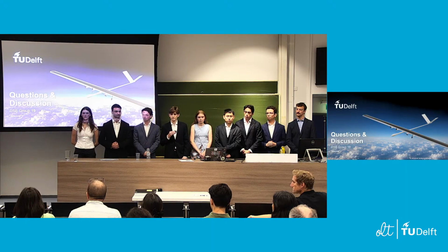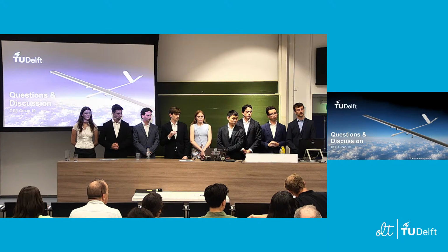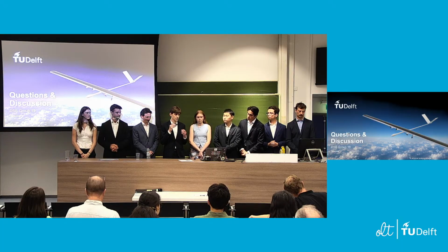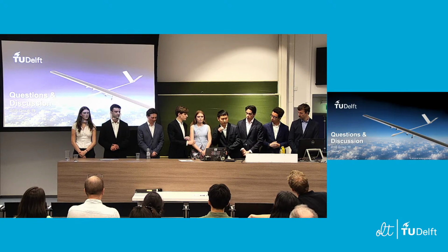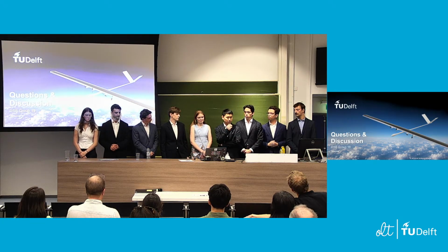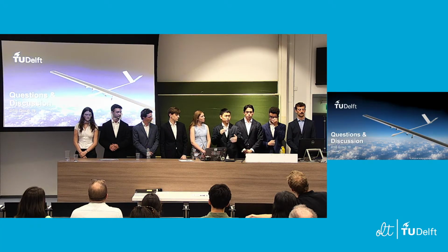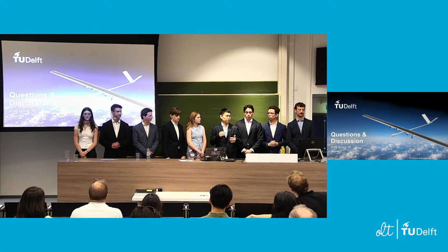Any other question? Last one. You referred to your power consumption and your power need. Was it also related to the power need of the scientific equipment, or payload? So the question was if the power need that we considered was also related to the scientific payload. Yeah, it's related, and we also need to consider the heating power for the sensors, because some sensors cannot operate at that altitude, where the temperature is around -50 degrees, and they might not be suitable at that temperature. We need additional power for heating as well.